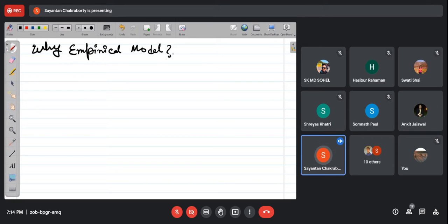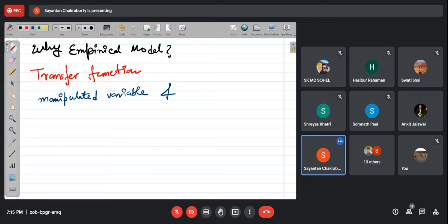Now, in contrast to that approach, there is a fundamental model in control-oriented process identification, where your objective is to design a control system for the given process. Our objective is to obtain a transfer function model. That is very important. The purpose of the transfer function model will be that it should reflect the dynamic response relationship between the manipulated variable and the controlled variable.